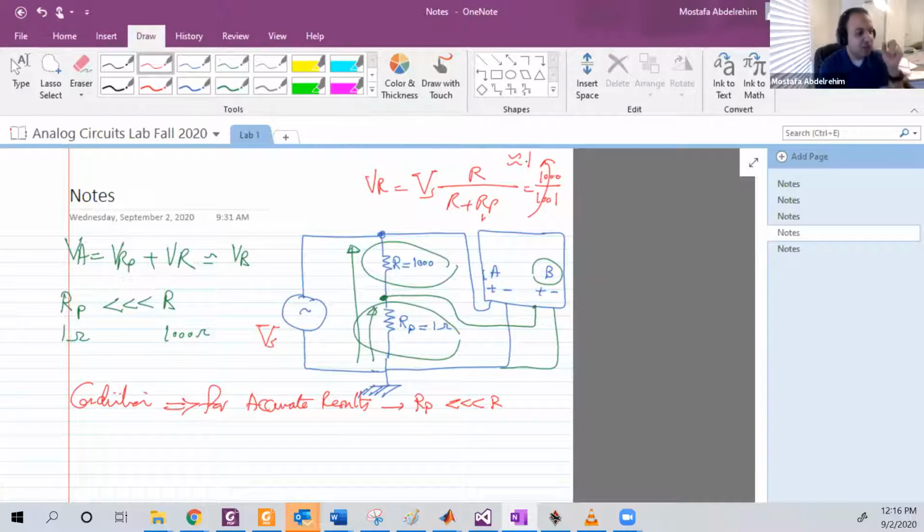The real oscilloscope has only one common ground, so the ground of channel A is exactly the same as the ground of channel B. In the practical world you don't even need to connect it, because the two grounds are internally connected and the ground in channel A already did that for you.